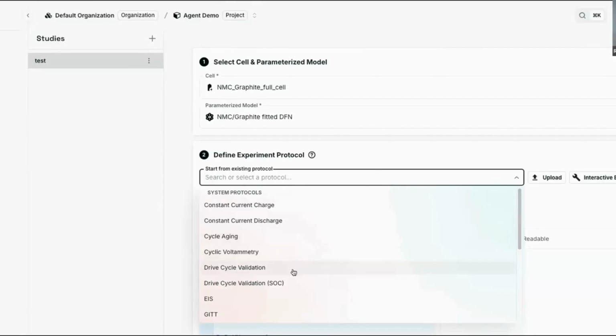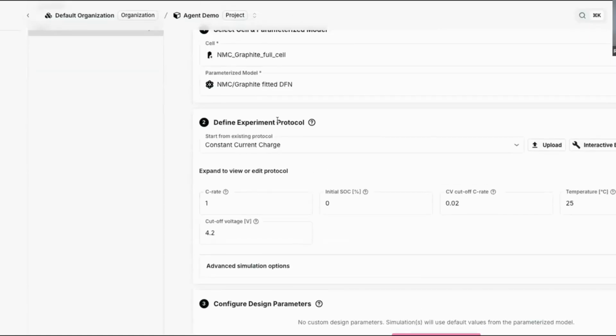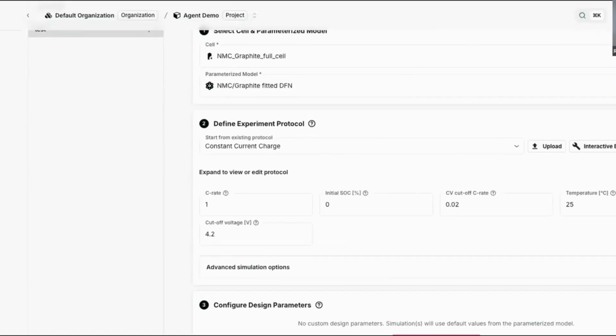I might be doing some CCCV or something, and all of this the agent can configure as well. So I could say, set me up this simulation of an NMC cell, set me up this simulation using LFP. If you've got the library of materials, you could build models with those two different cathodes and then do that comparison. Essentially, we're just giving it the skills to make calls to PyBaMM and to the Ironworks framework. So that was a very long-winded way of saying yes.